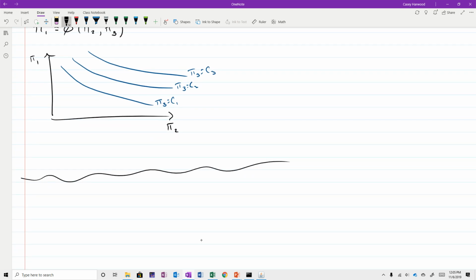For more than 3 pi terms, it starts to get impractical to try to come up with experimental correlations, right? Because then you start getting into higher dimensional space. You have to do a lot of experiments, right? We talked about before. If you have 4 or 5 pi terms, then in order to produce this experimental correlation, you basically start having to perform hundreds or thousands of experiments in order to get a full factorial design of experiments. So for more than 3 pi terms, this is where it starts to become more economical to do model scale testing, and that's what we're going to talk about in the next lecture.